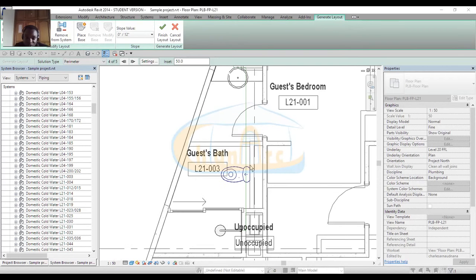In this case, for instance, on this side you can see that the WC is the farthest away fixture. So this is what is going to drive the bounding box location and the offset. Let's for instance set it to 0. You will see that now the branch is right onto where the connector is located.